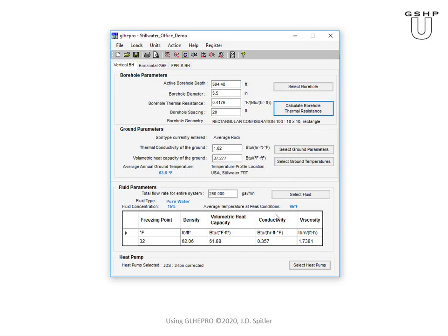Okay, so first of all, we're not going to be able to do 600 foot deep boreholes, or I'm going to assume that our drilling contractor is going to balk if we tell them it's 100 boreholes 600 feet deep. So there are several things that we might want to look at to try to improve the design. We're pretty much stuck with the ground conditions. We could possibly go with a slightly higher temperature. So maybe we just check that right now.